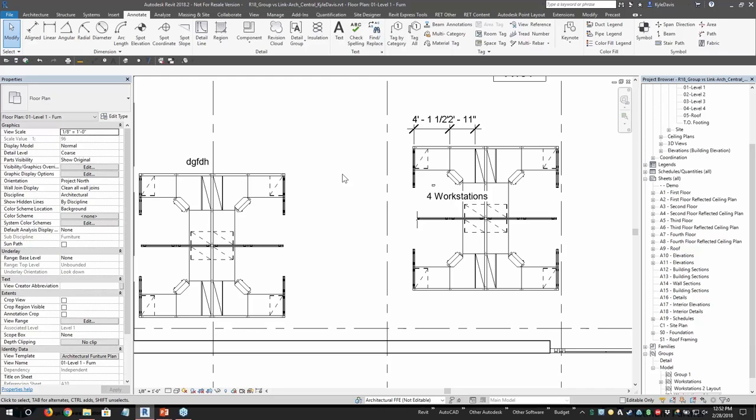And if you're doing big projects, you might want to break up your project into multiple files so that you can link in the others. So you might have a shell model, an interior model, and a furniture workset model. Your project can be really big, and all in one file could just be too much, and your users are having slowdowns. If you do it as links rather than groups for big projects like that, you can unload those links, work faster, and turn those worksets off. It works a little bit faster than groups themselves. So there are some benefits of linking versus groups in certain conditions.